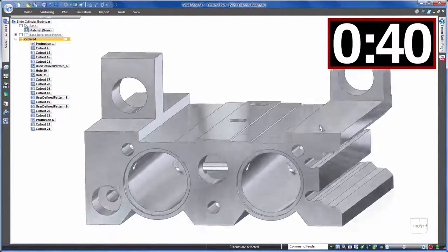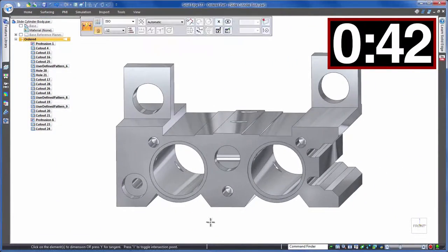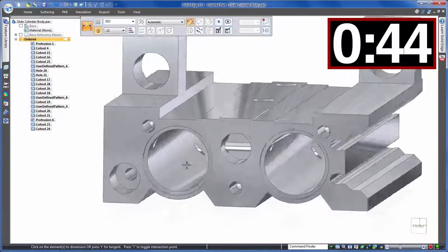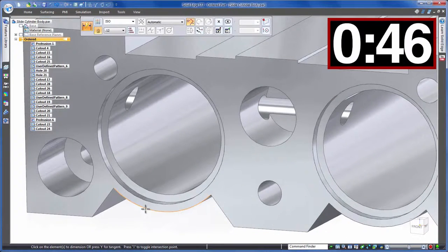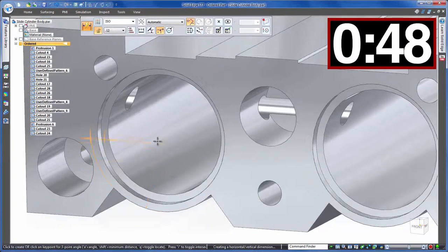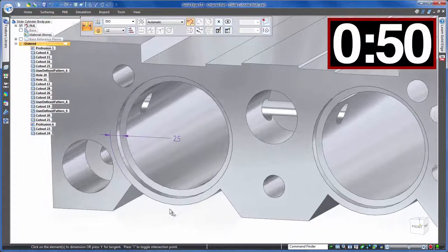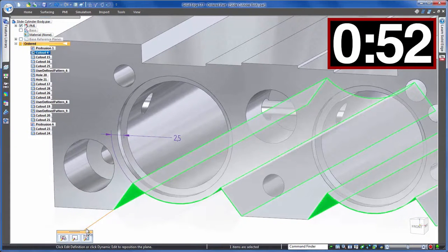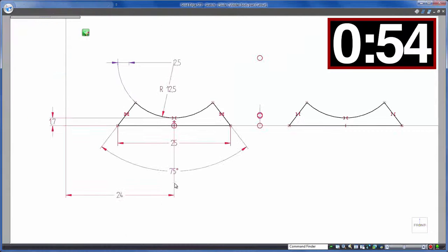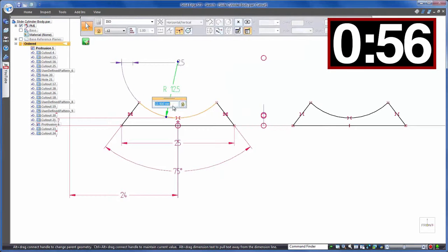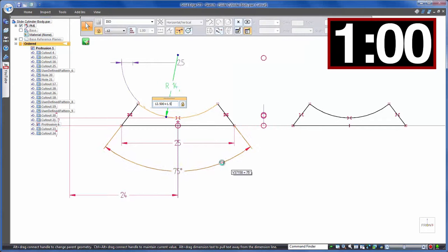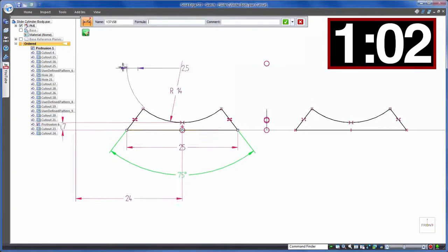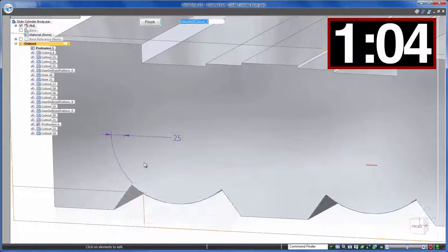Back to history-based for the next change, and before we make any edits, we need to find out how much material we currently have between the cylinder and the cutout. Measuring it finds it to be 2.5mm. We need to make this a total of 4, so we'll add 1.5mm to the radius of the cut. Again, we'll go in and edit the sketch of the feature and use Solid Edge's ability to enter equations in the dimension box to simply plus 1.5mm. Rebuild the model and...